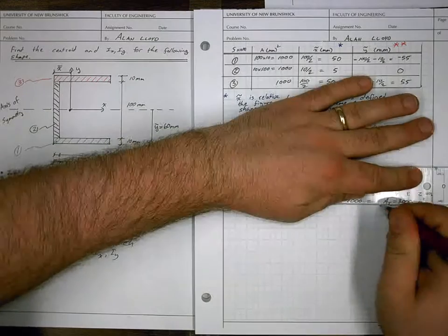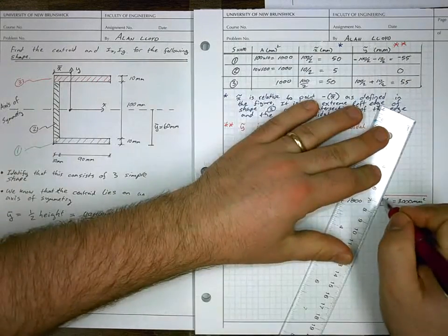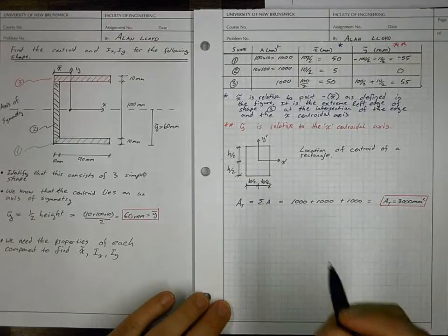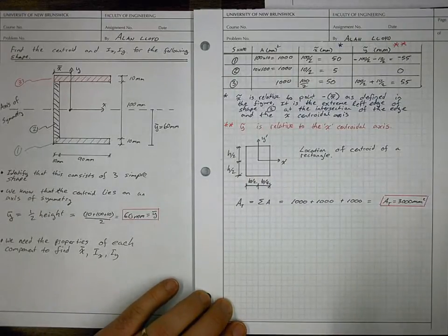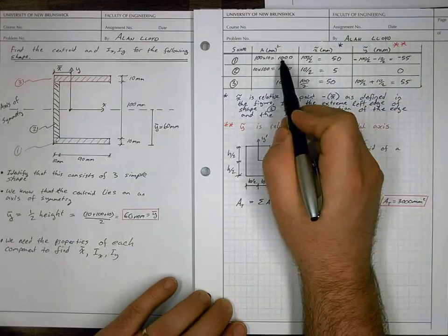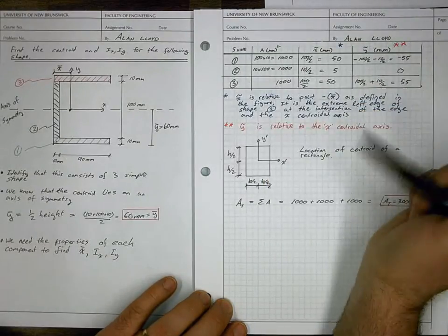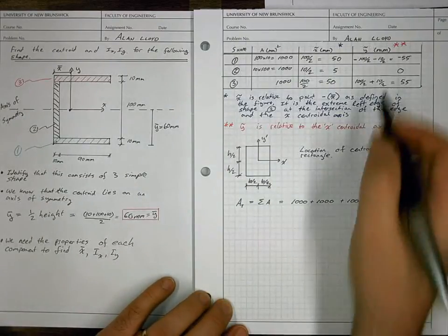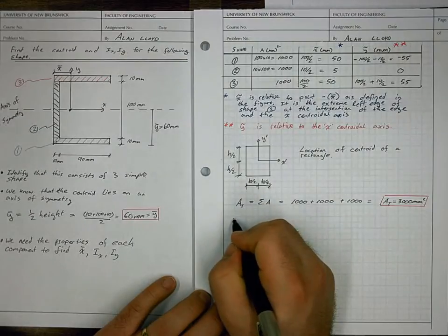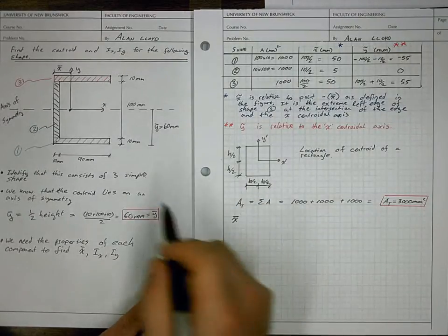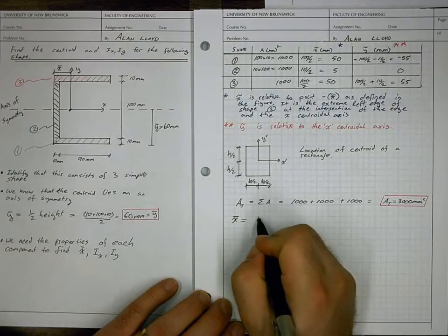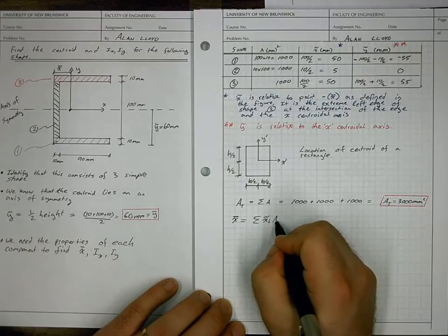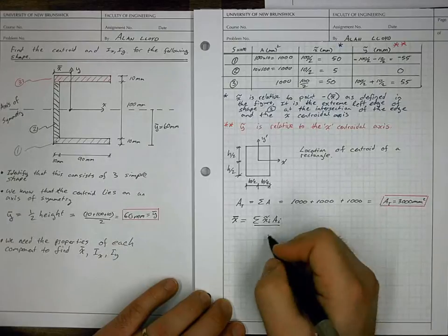Now if we're going to take the moments of the areas, we need to take the quantity of x tilde times area for that component. So for each one, we're going to take area times x tilde and area times y tilde to find our axes. Since we already know our y value, we don't need to follow through with the second thing I said there. So if we look at our equation here, x bar, as we've defined it there, is equal to the sum of x tilde i, area i, divided by area total.